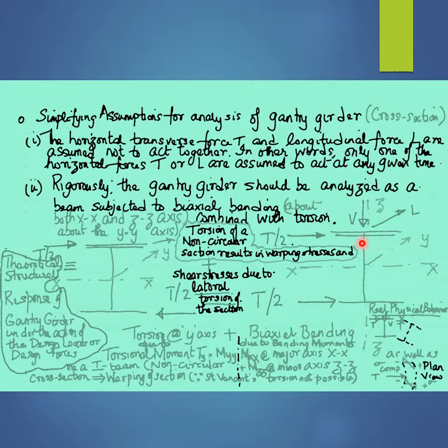And the bending about the major axis X of the girder cross section, that is illustrated in this figure, and the bending about the minor axis Z of the girder cross section is accompanied by a torsional rotation of the girder cross section as qualitatively illustrated in this figure